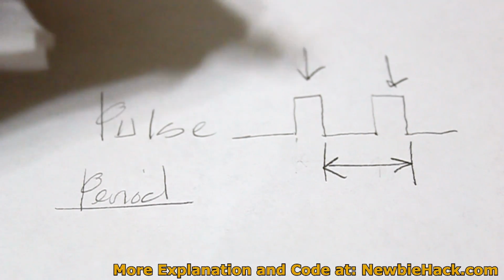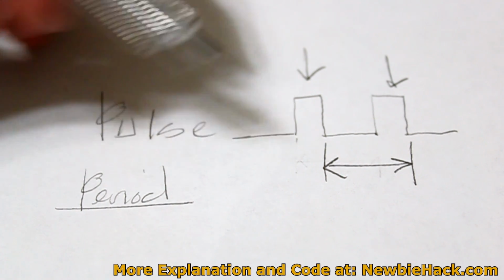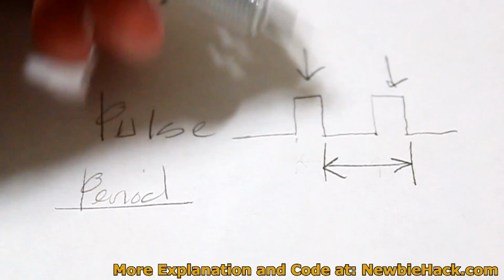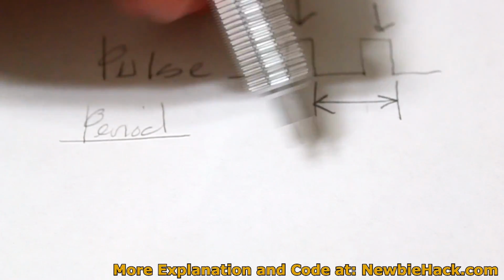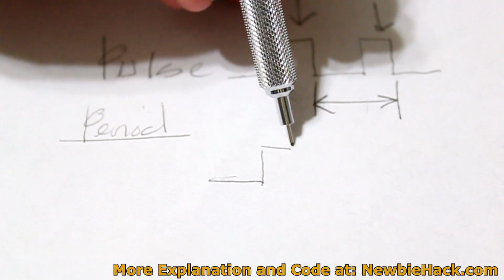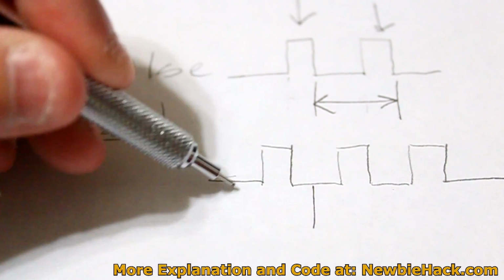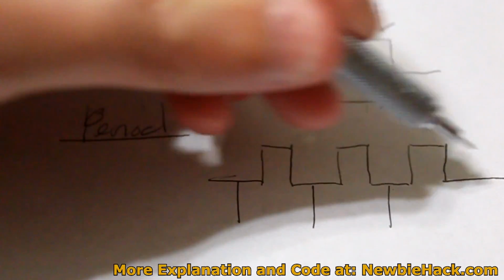And you also have phase correct PWM, which is really just taking the period, which is here, and shifting the period so the pulse happens in the middle. As an example, let's just take the same pulses that we have. And the pulses would happen in the middle of the periods. The periods are still constant.